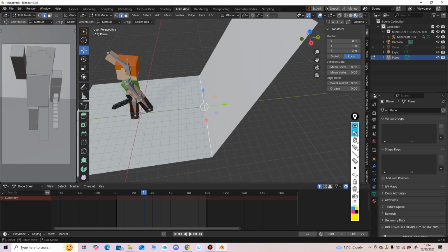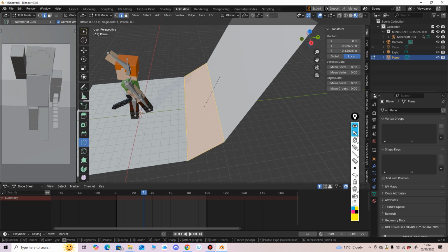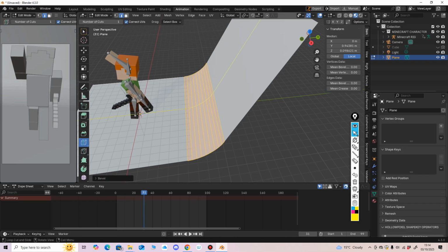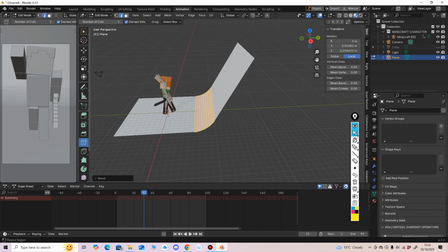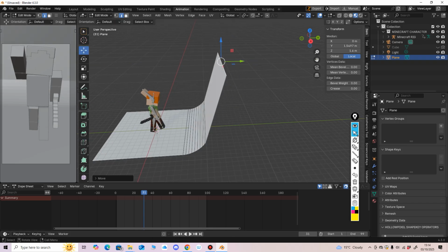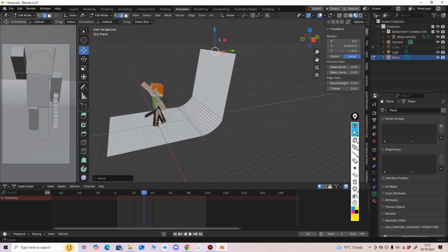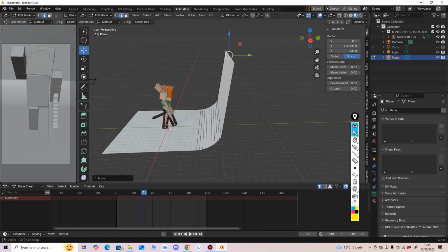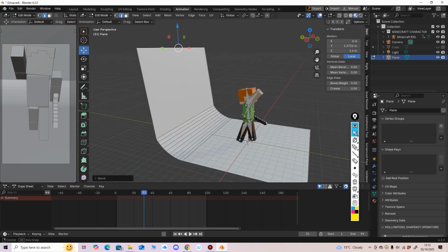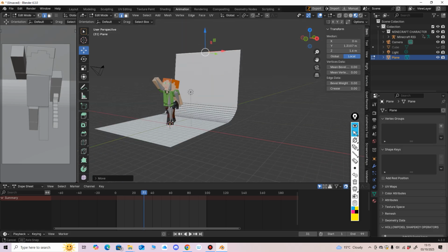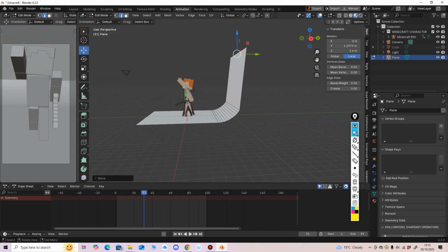Known as a bent plane or an infinite plane. If you go to Control B, bevel that edge, swivel your middle mouse. That's created a bent plane now, which is known as an infinite background, which is what a lot of people use for lighting items, simple or sometimes complex. So that's your infinite plane.